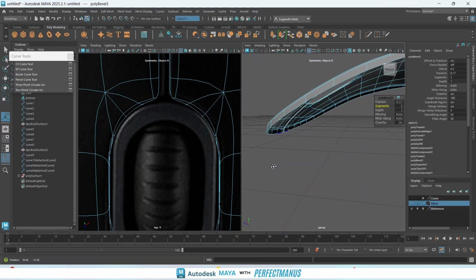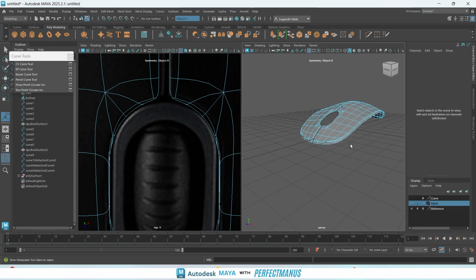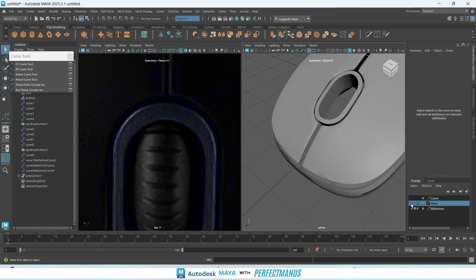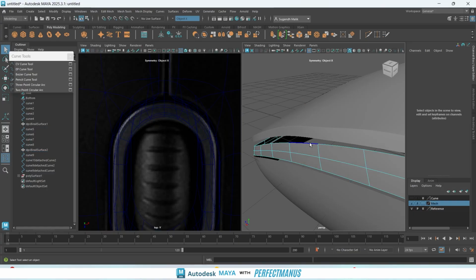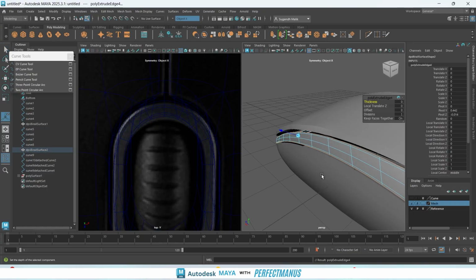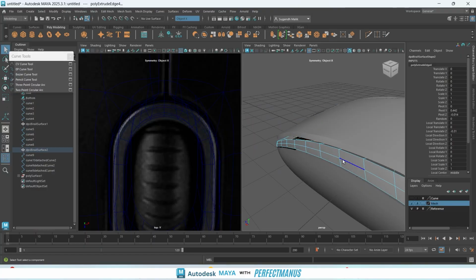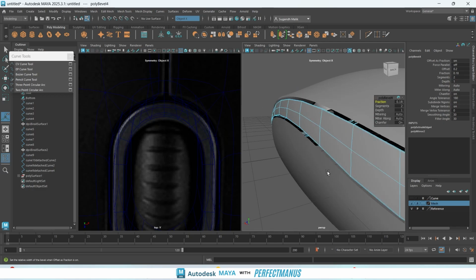Okay, and then there's something like this on the top one. And for the other parts, let's move on to this one. While we are creating this, your every mesh part is created. You do the same thing: you go on its edge, you extrude them, you give them a local offset, and onto the edges, you bevel it. You give them at least two divisions. Increase these values to something around 0.18, 0.15, and then smoothen it.